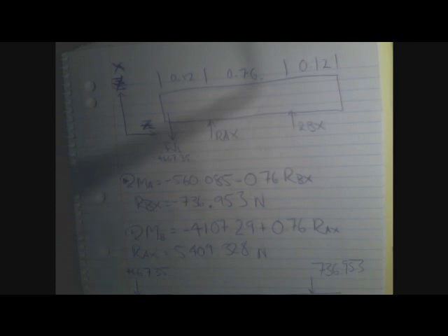So once you've done that in the YZ plane, you then do it in the XZ plane. As you can see, I've drawn this one a bit bigger so it's easy to read. It's the same deal, except we replace the weight of the pulley with our static load, WS, which we calculated before doing our hub loads for our pulleys and belt section. You go through it again and calculate your reaction forces. This time they're your bearing reactions in the X direction as opposed to the Y direction. These will come in handy later when we're calculating our bearing reactions.